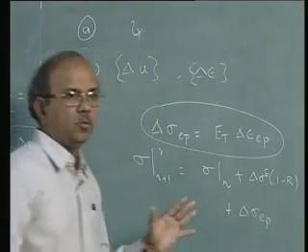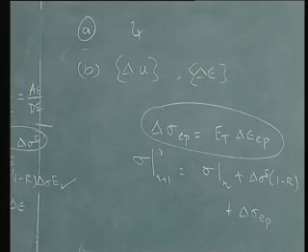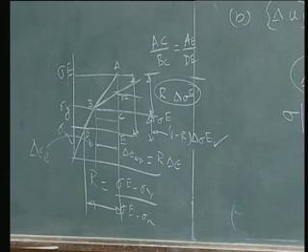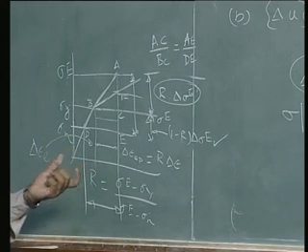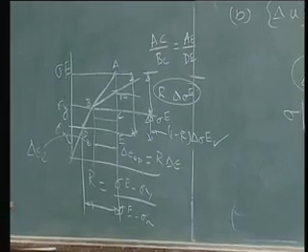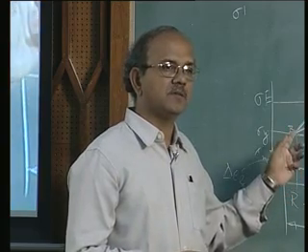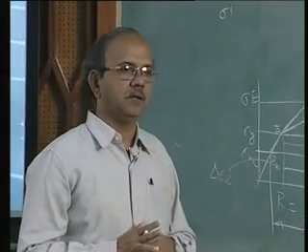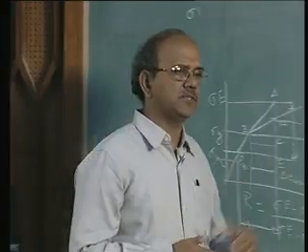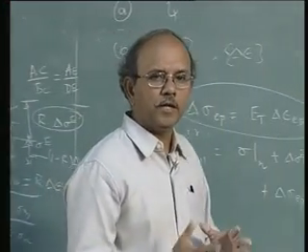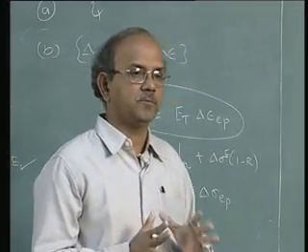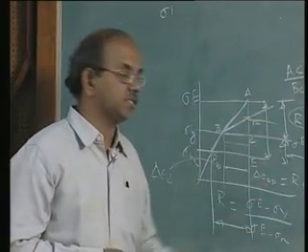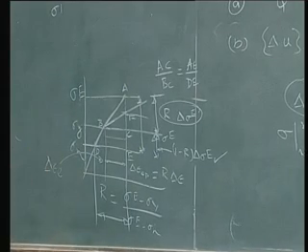Though I am not very happy right now because of the issues I have raised, nevertheless, for many problems this seems to work. And when does it work? Especially when the load steps, and hence the corresponding delta epsilons, are not very large. We have to make some adjustments, but many times when the time steps are small, explicit stress integration schemes are perfectly all right.